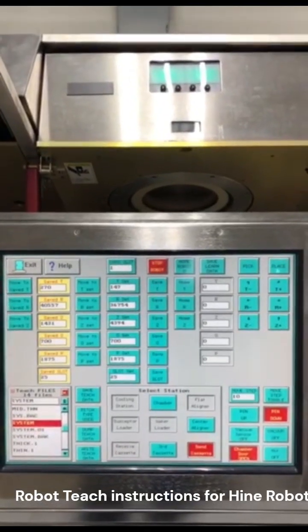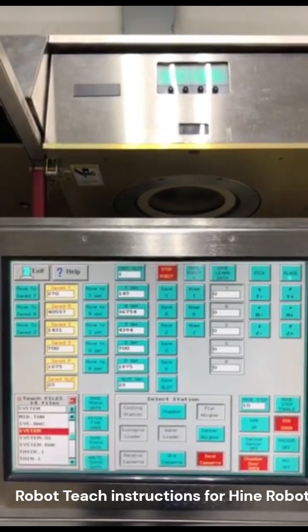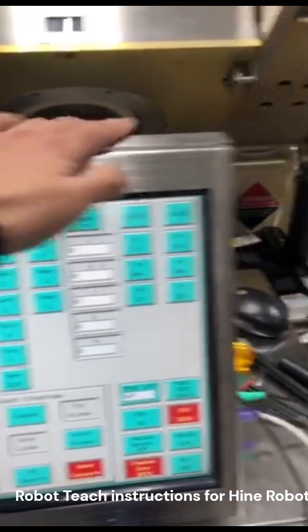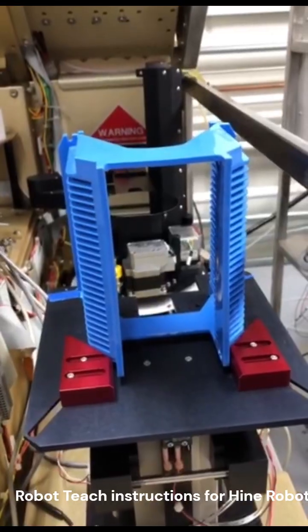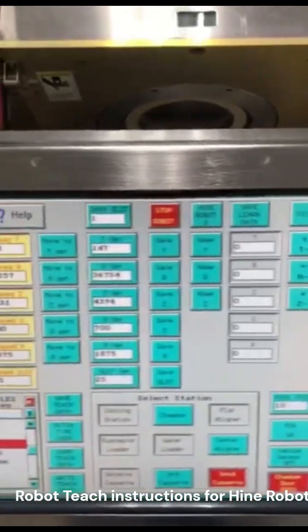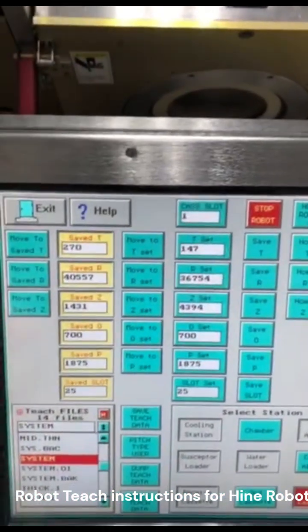In this video, I will show you how to finely tune the robot teach process using the software without manually moving the arm. For example, let's say you are picking from your cassette, but you need to change the Z of the first wafer by small increments. In order to do that, let's say you want to change Z.